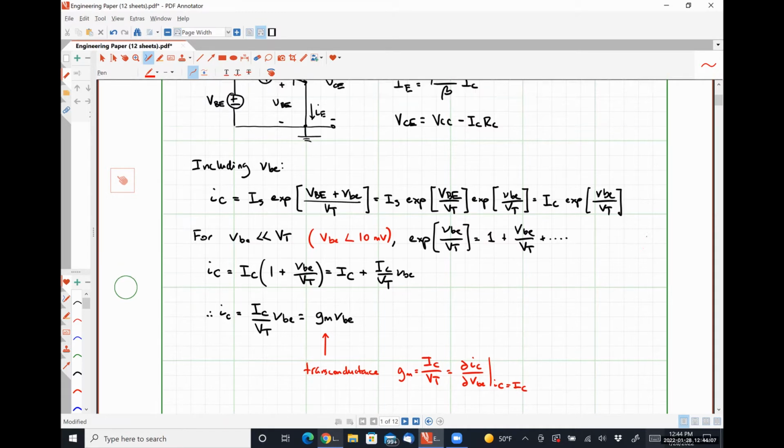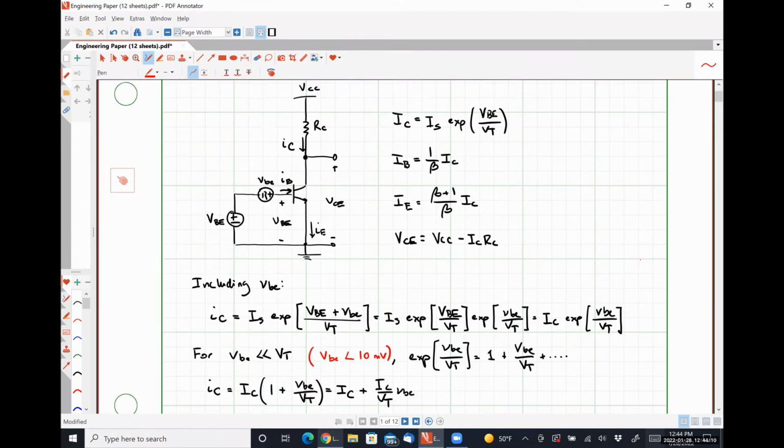If I can scroll up here real quick, what we'll find is that the inclusion of a load resistor here converts that transconductance amplifier into a voltage amplifier. Because our output voltage is dependent on the quantity VCC minus IC times RC, the voltage drop over that resistor RC changes as that small signal collector current changes. So it's going to give us a voltage at the output that's superimposed on top of that DC operating point.